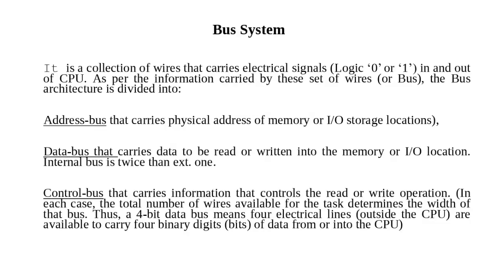Okay, and there is another terminology, the bus system. A bus is actually just like a wire. In a digital computer system, it is either logic 0 or 1. Logic 0 means like 0 volt, and logic 1 means like 5 volt or 10 volt, it depends on the system. So the three types of bus are: address bus, data bus, and control bus.